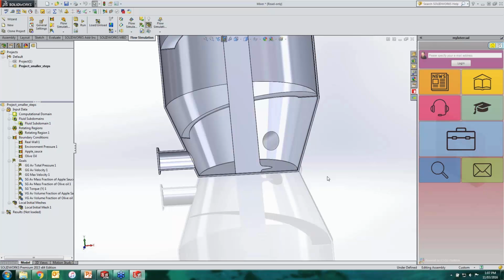One thing for sure, guys: the second approach, which is this one with sliding, is definitely much more time consuming. It depends on the project size and the domain geometry. It can take from hours to days or even weeks. So it's very important to understand what you want to achieve, what you have to simplify, and make sure that your mesh is all optimized.